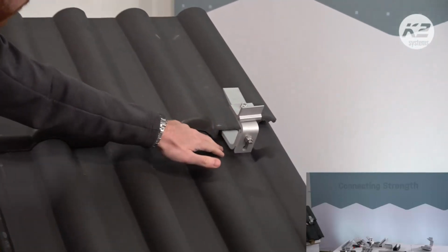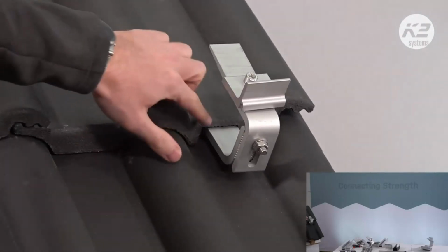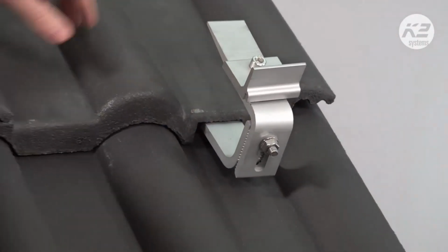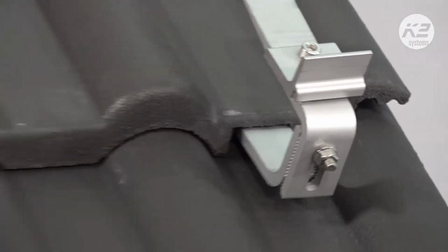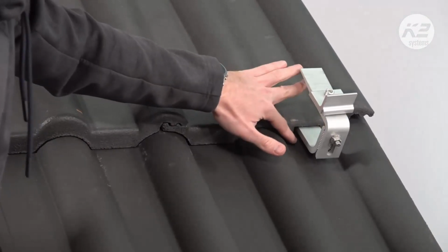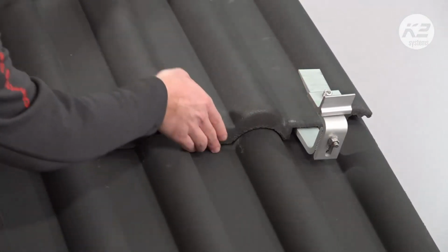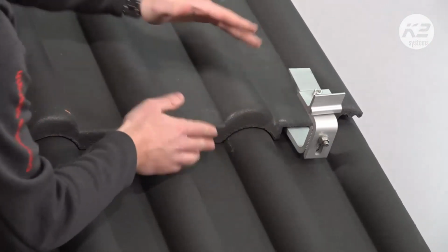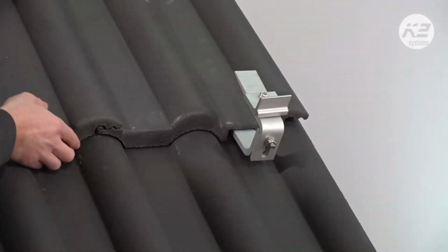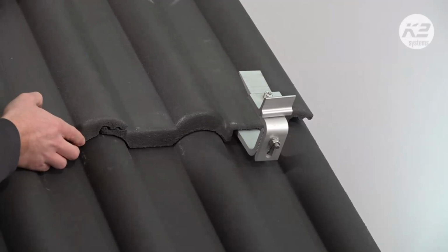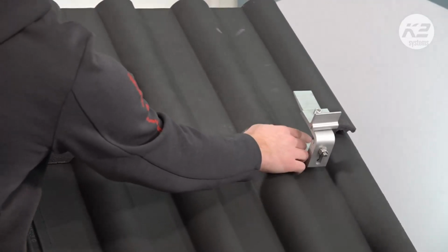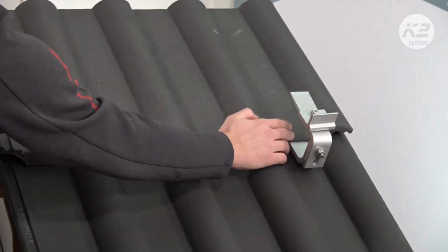As we see here, for this type of tiles, from this side we have cut some part of this tile in order to keep the same elevation, of course, of the whole module field. What if we did not cut this part? This tile will be elevated a little bit like this, for example. I cannot move it now, but this part will be a little bit elevated, and then it will affect the other part. It will be elevated also like that, and the effects will go along my roof. So it's important that we cut these places here.